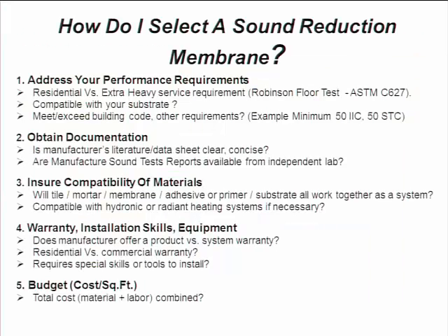Let me touch briefly on how do I select a sound reduction membrane. We just looked at some of the comparative products. We talked about the different test procedures. And what you're going to want to do is look at whether it's going to be residential in nature, or is it going to be heavy commercial in nature.